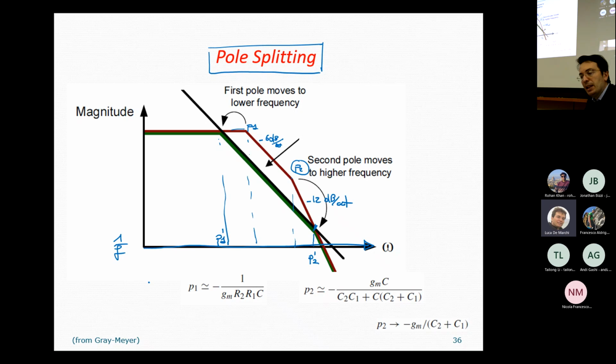So we are decreasing the output by virtue of this application. So the slew rate for negative transitions is basically equal to I7 minus I5 divided by the loading capacitance.